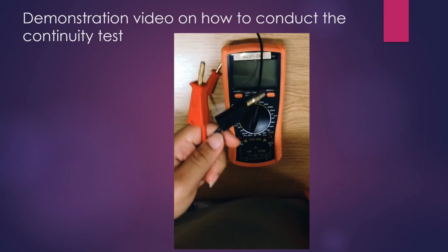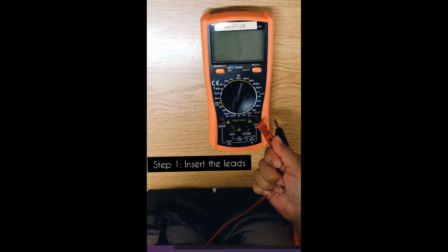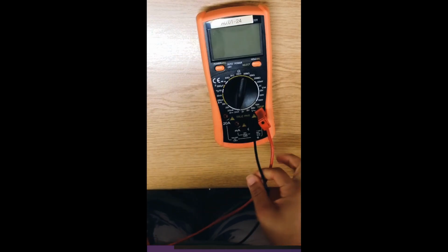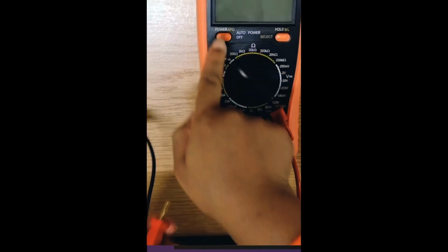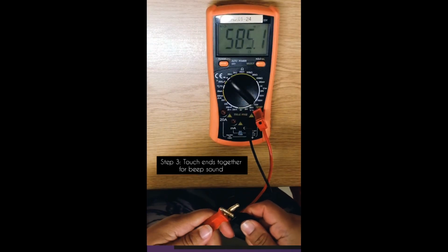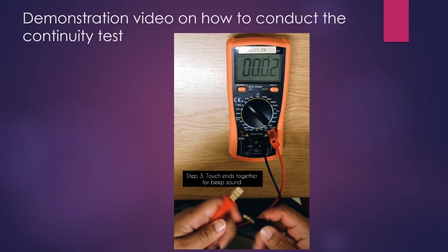Here's a short demonstration on how to do the continuity test. Like I said, you insert your leads, you change to the continuity function, and you touch the ends of your leads together to get the beep sound.